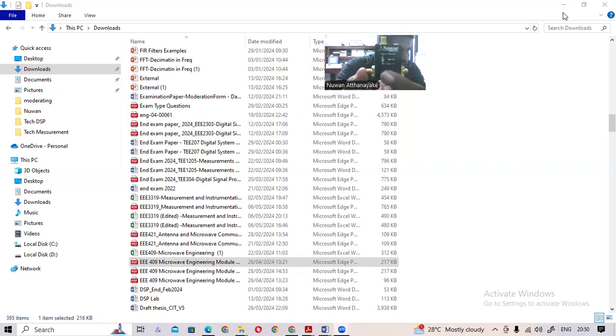If you give a signal here, DC plus AC signal, for example, a sinusoidal signal with a DC shift, so that is a sine signal and DC signal combination. This capacitor will pass only the AC signal. It will not pass the DC signal. So here you will get the 0 DC shifted signal. That means the DC part is removed.